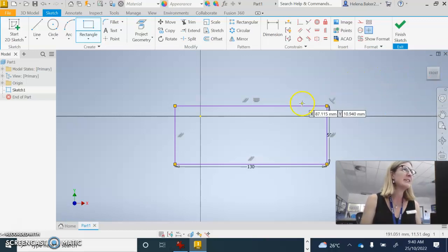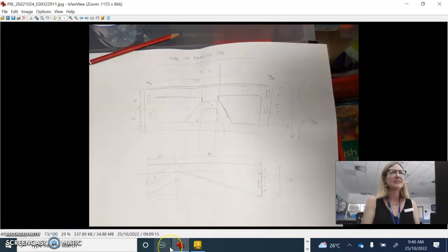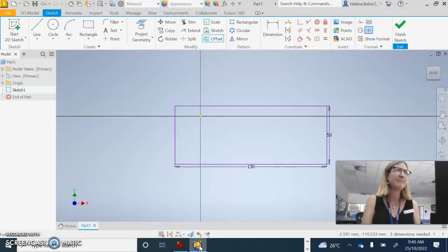So we're now going to use the offset tool, and I'll just click my drawing over here to describe what we're going to start with modelling. So I think what we will do is we might start with these little tabs here, which is where we're going to have our intersecting parts. So this design is made for acrylic or ply. We're working with 3mm material, and so we're going to create little slots for these tabs to fit into. Alrighties, so back to Inventor.